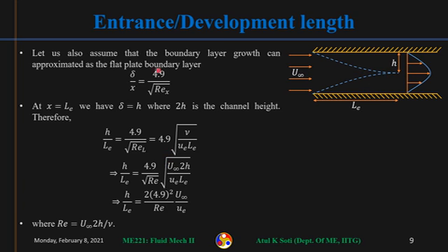So what we are saying is that locally, anywhere, the boundary layer thickness is being approximated by the flow over a flat plate. So locally, we use the local free stream velocity, ue. What is ue? That we need to find out. ue is the central inviscid region velocity. That will be related to u infinity somehow, because this region is going to accelerate.